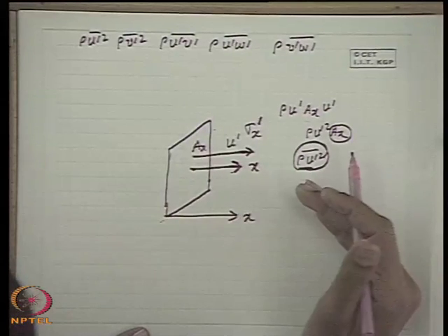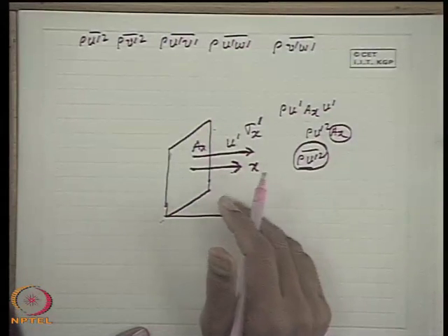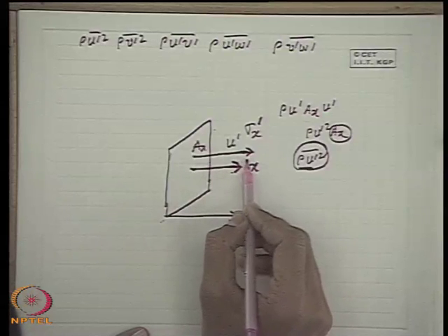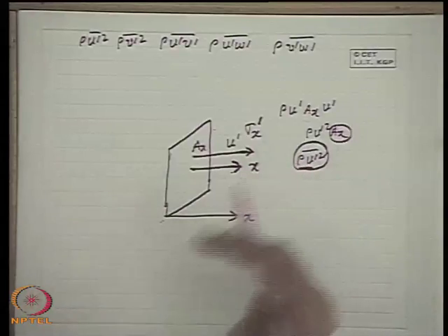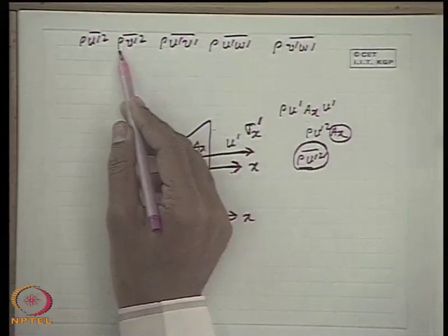Because of the molecular momentum transport, the laminar stresses arise, which we have already discussed earlier in the beginning of this course. Similarly here, because of the momentum transport associated with the fluctuating components, that means the momentum transport by the macroscopic mass of fluid, some additional stresses are coming. Now, let us see what is rho v dash square.